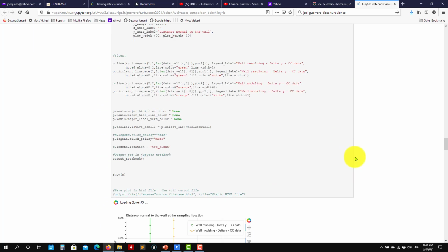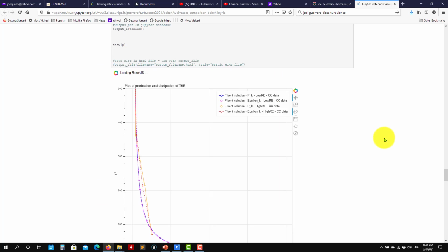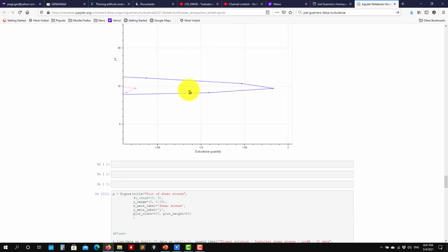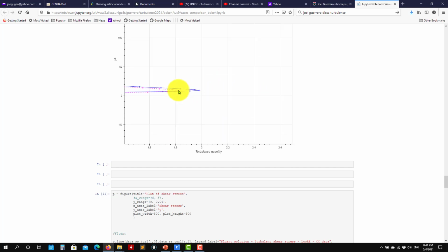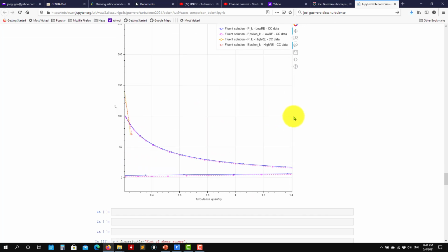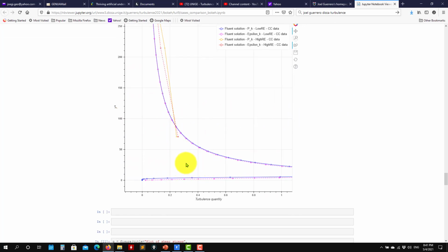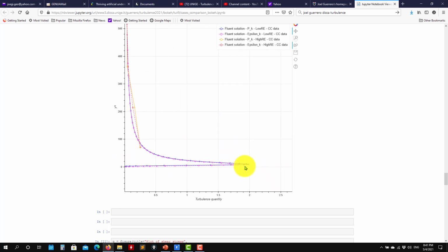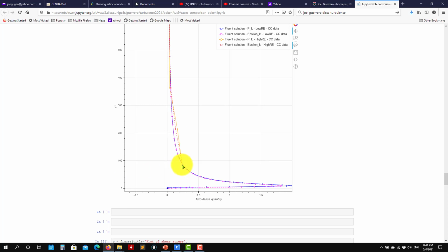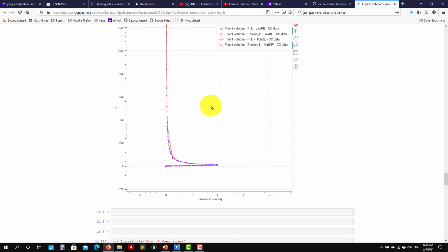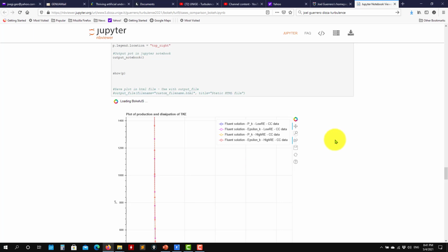And all the plots here, this is the turbulent kinetic energy normalized by the wall. We have seen that this one peaks somewhere in the buffer layer. So you see that you have this behavior. And then look at that in the wall modeling, all this region here, you can see clearly that has been modeled below here. Nevertheless, we are not capturing this phenomenon here. The wall function is actually enough to get a good value here and then a nice prediction on the rest of your profile. So we just save this data from Fluent and plot it here.